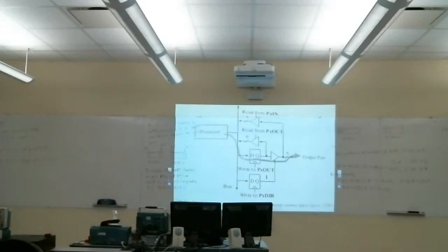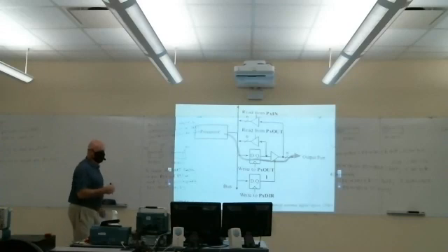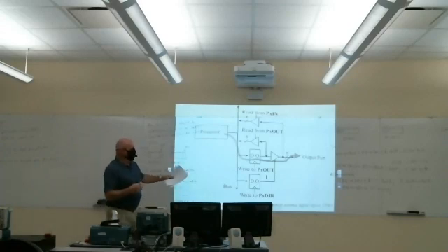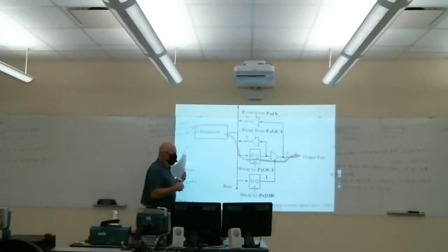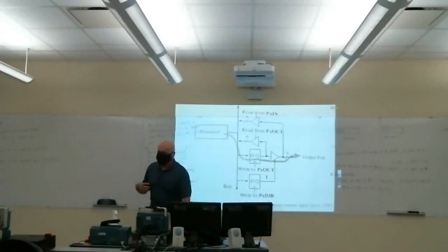This typically isn't changing while your program is run. You set up a particular pin as general purpose input output or its alternate function, and then you would set it up as either an input or an output pin. To make it an output pin, you write a 1 to that particular bit in the direction register.